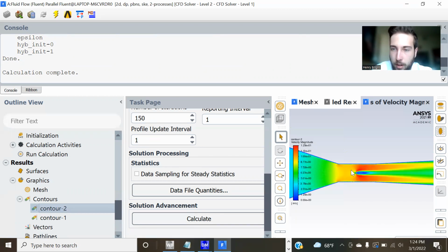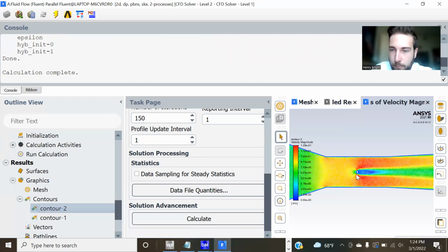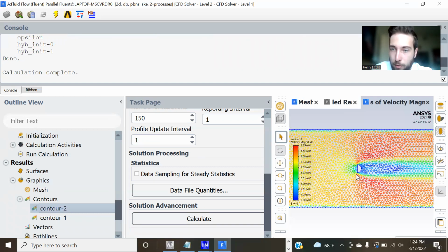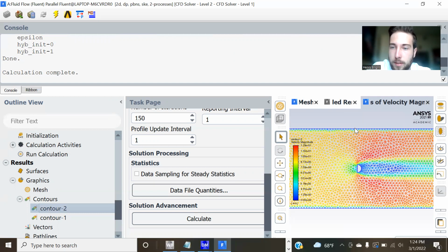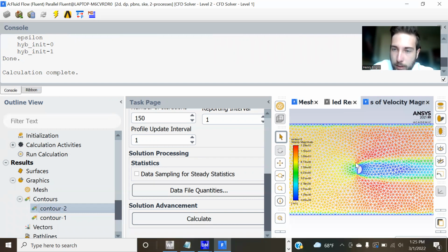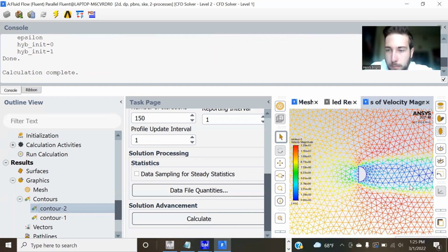And then if we zoom in on our object, you're going to see the opposite sort of pattern as static pressure, where you've got that wake region, like I told you about, forming behind the object. We've got a lower velocity, and could even potentially get some flow separation. We might even be able to see that in the streamline patterns, not to spoil anything too soon, but we will see. This is exactly what we'd have expected for our object, and that's how the velocity contour looks.